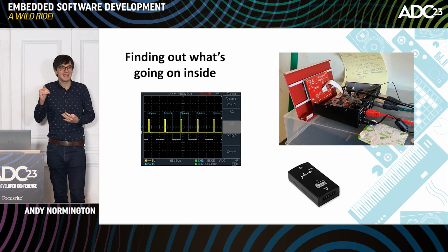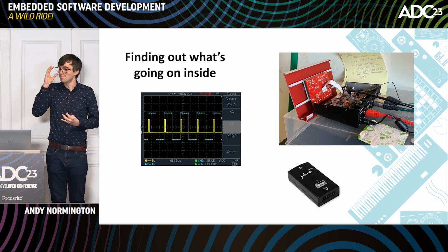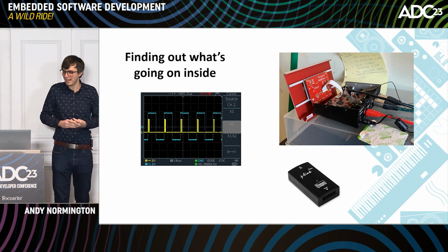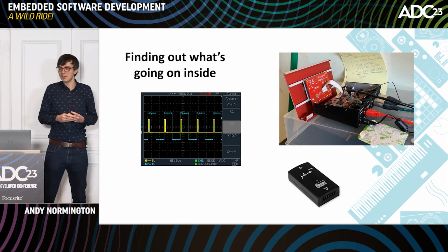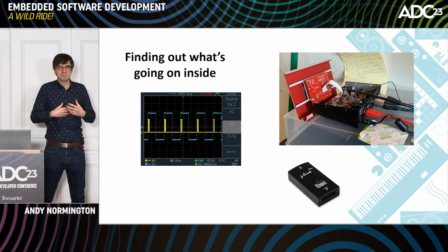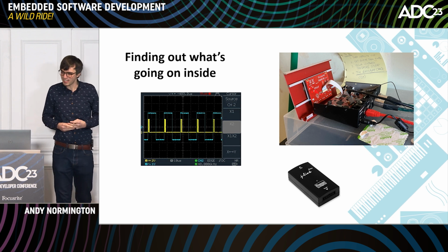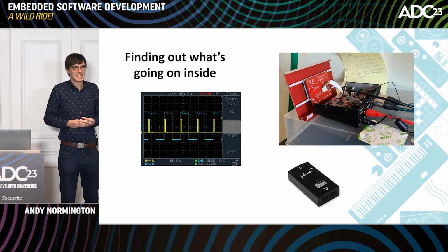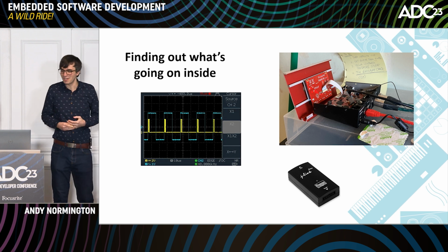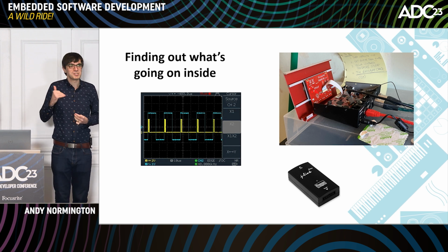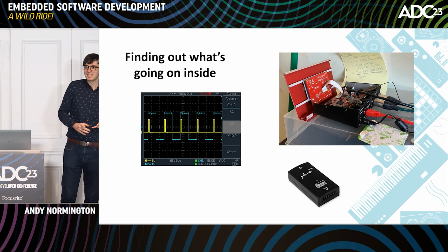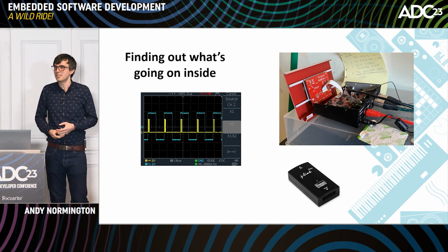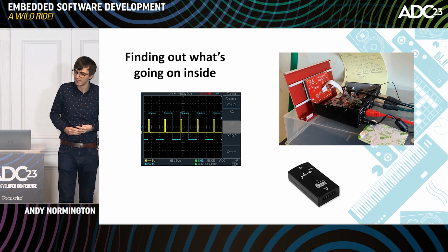The step above that is that we can have a dedicated debug port, and we'll pretty normally do this on our hardware. There's a slight compromise here because it's a dedicated transport for debug. We can't run that over any of the customer-facing interfaces outside the unit, so we have to have some pins dedicated to that. It's normally only 3, 4, 5, it's not a big deal. And then we can run some GDB fork on top of that, get normal kind of GDB features with some plugins to give us context for the peripherals that we've got on the target and the OS that we're using.